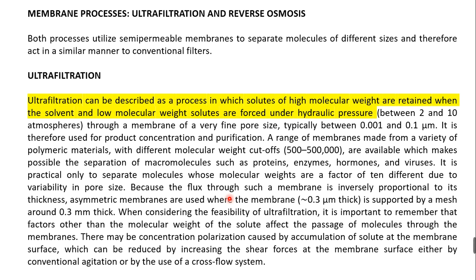But the life of the membrane depends on the raw material we are going to use for the filtration. If it is a slurry or something, it has a lot of solid particles and maybe some other sedimentable materials that may clog the membrane. So before passing the material for filtration, you have to ensure that there are no sedimentable particles within the solution. If there are, that will reduce the life of the membrane, and all the pores will be clogged, and automatically the cost of the operation may be very high.